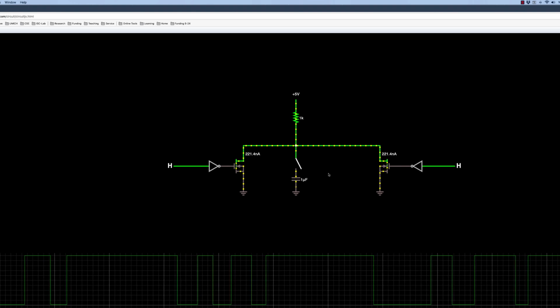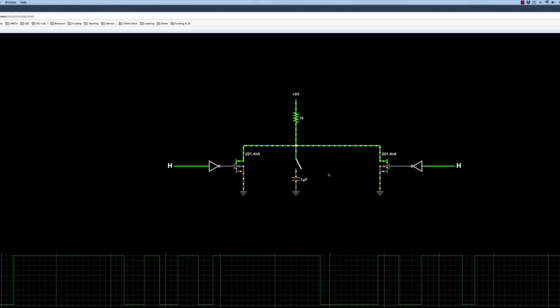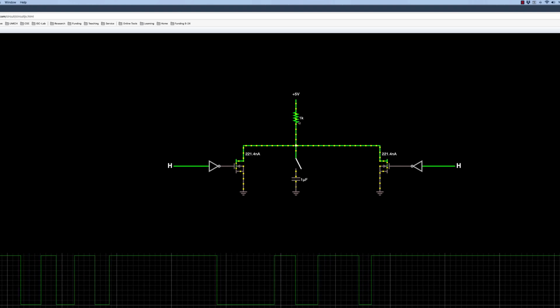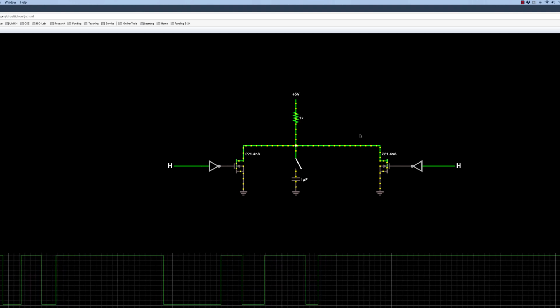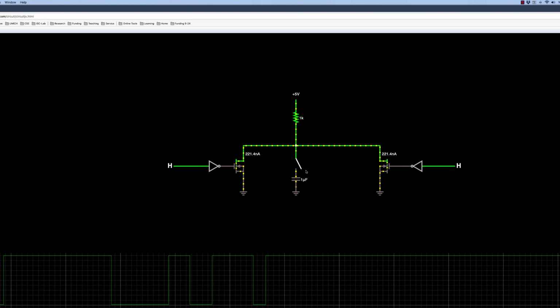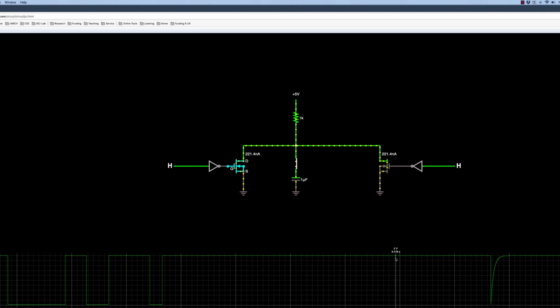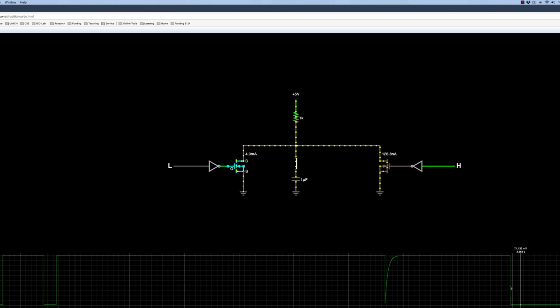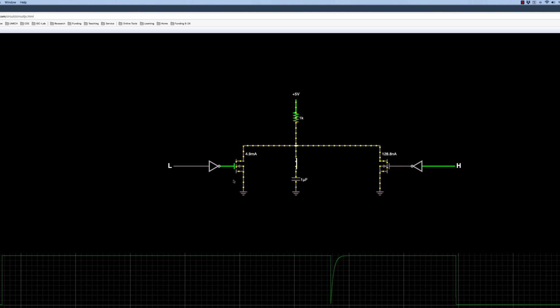Okay, all right. So just to drive home, the next comment I want to get your head around is why we need resistors of different sizes, because I can change this in this simple simulation to whatever I want and get nice square waves. So let's add a capacitor in here, okay? And if I drive this low, you can see it went low very quickly, right? Because I'm just dumping as much current as I can through this.